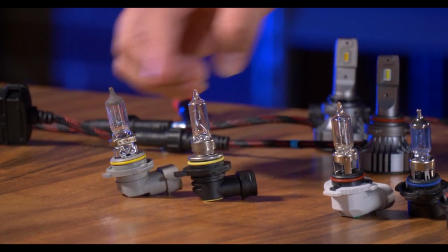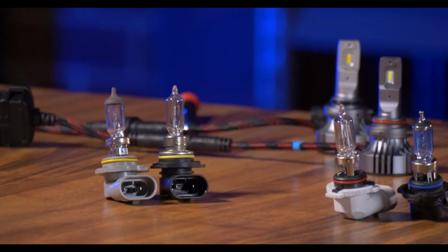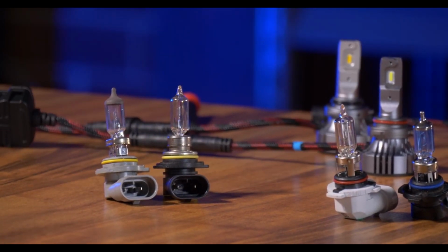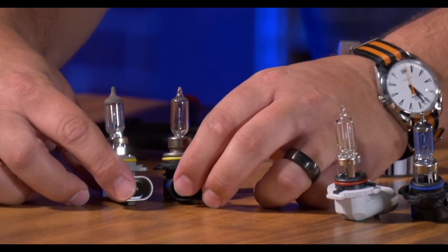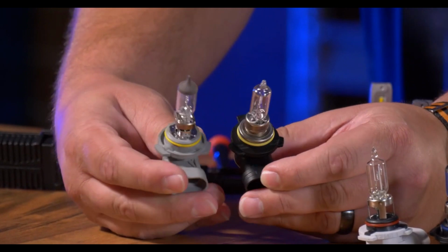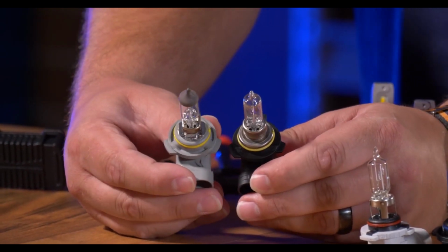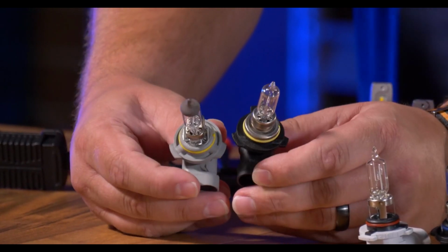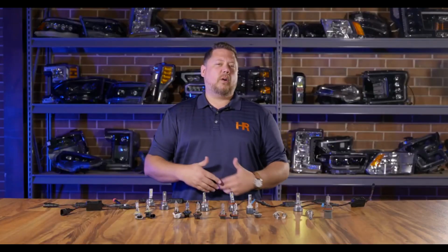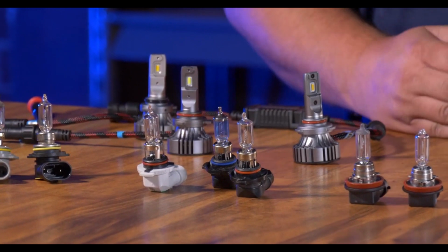They have very similar looking bulbs up top. The connectors are identical. The O-ring diameter is the same, so they fit all the different applications, but as you can see, the three plastic tabs are slightly different. So you're going to find somebody who makes a bulb that fits both of these, or you're going to find somebody who makes a 9006 and a 9012. So you just have to do your research. Find out what you have, and then find out what's compatible with it. Another example of the same thing is with 9005 bulbs.